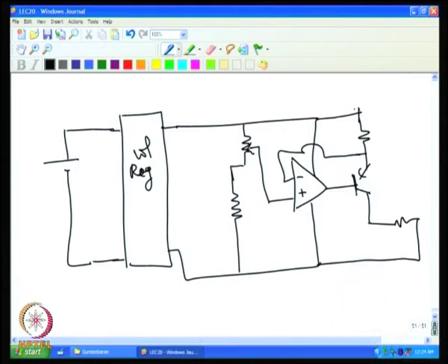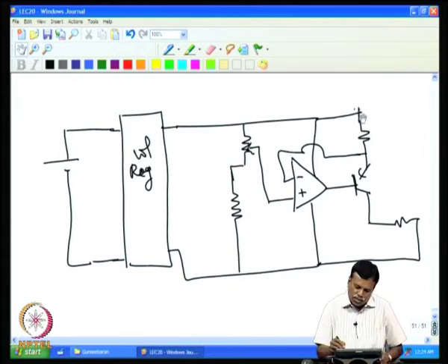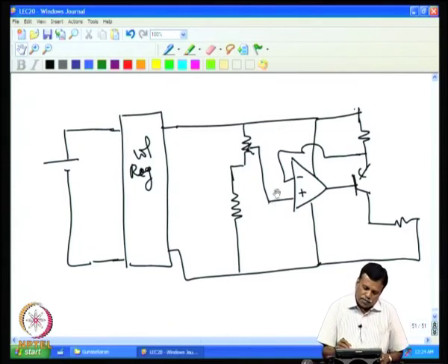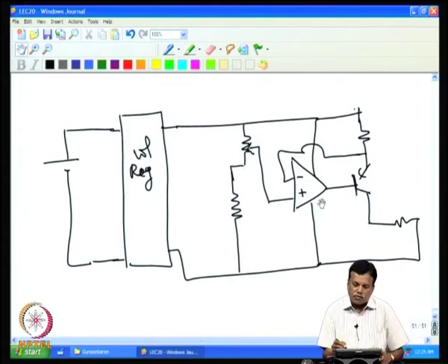So, in this case our original issue was that the supply of this is the same as this potential, no current is there, there is no voltage drop at 0 current. So, this also goes up to the supply voltage, and the potentiometer is moved to one end, and this one also goes to the supply voltage, and the op-amp input will not accept exactly the supply voltage. The input has to be a little lower than the supply voltage. So, this was the problem that we had discussed in the previous circuit.